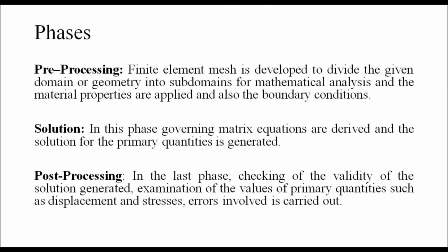In the second phase, that is the solution phase, the governing matrix equations are derived and the solution for the primary quantities is generated. In the third phase, called the post-processing phase, the validity of the solution generated is checked, and the values of primary quantities such as displacements, stresses and the errors involved are examined.